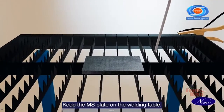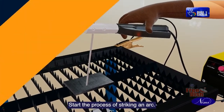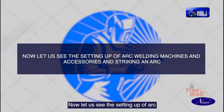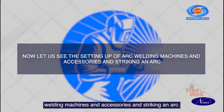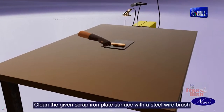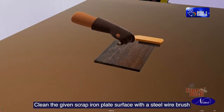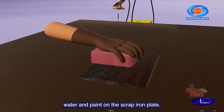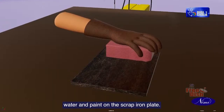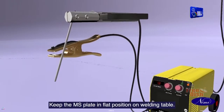Keep the MS plate on the welding table. Start the process of striking an arc. Now let us see the setting up of arc welding machines and accessories and striking an arc. Clean the given scrap iron plate surface with a steel wire brush. And also clean for any oil or grease, water and paint on the scrap iron plate. Keep the MS plate in flat position on welding table.